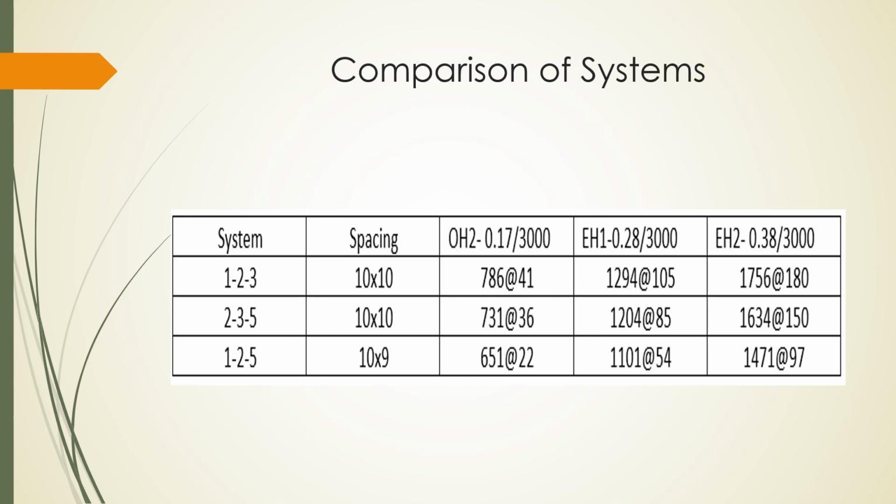The EH1 would be a higher combustible content with little or no flammable liquids. It might be a printer or a wood shop, something that had some kind of fuel loading there. And then an EH2, extra hazard 2, would be moderate flammables or combustible liquids, and also plastic processing and solvent cleaning, that sort of thing.